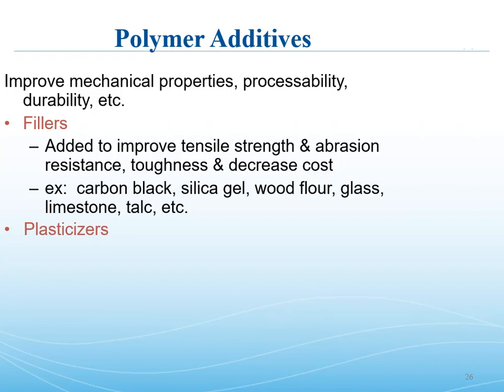Plasticizers go completely the opposite way. These are small molecules that basically provide steric hindrance. They get between polymer chains in both thermosets and thermoplastics. They open up the network and force volume and distance between chains, and they allow things to move a little bit. In the case of even network polymers, they increase what's called the free volume of the polymer. They allow it to deform just a little, even though it's still a network and it's not going to slip the way a thermoplastic will. It allows it to move a little more and can increase the fracture toughness.